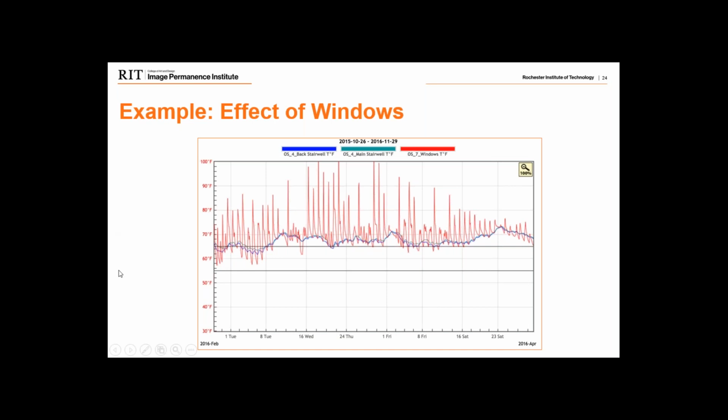row of books. You can see the same is not felt in the stacks by the main stairwell. They just kind of move along. And at some points, the temperature reached over 110 degrees. The really disturbing thing in some respects is that I say it's a northern city, and this was occurring during February. So we're seeing 110 degrees in the coldest time of year on the east-facing window. So what could happen during some of those summer seasons? It's something to keep in mind. In this scenario, we recommended boarding up the windows, covering them, and you can actually see that begins to happen around here and it starts to even off.